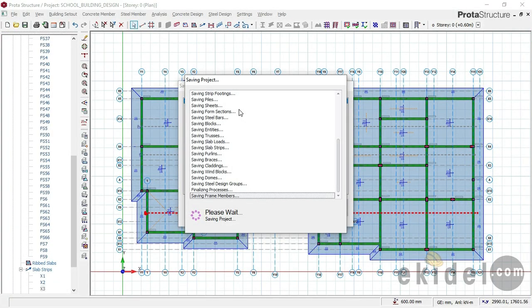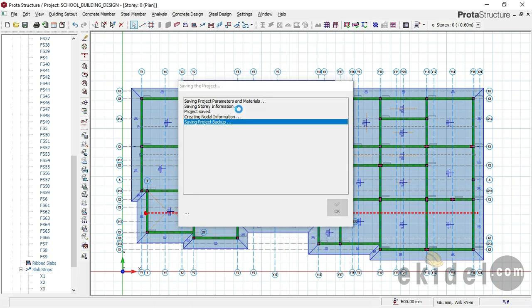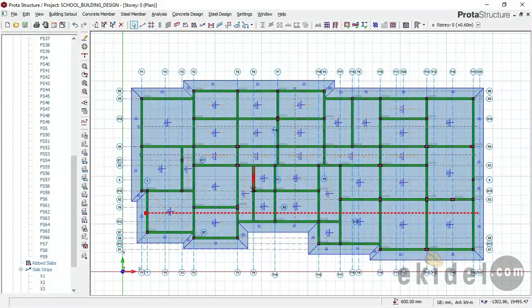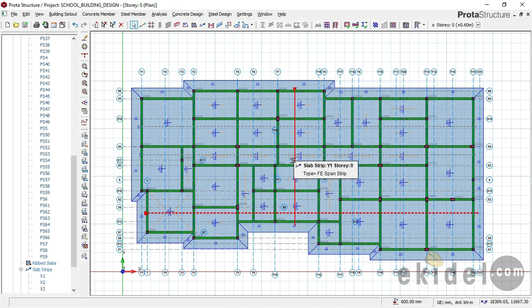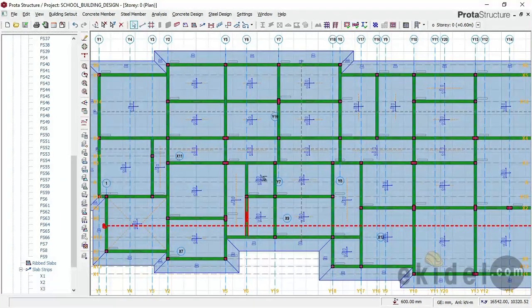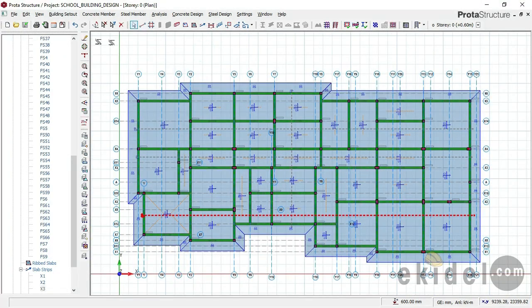If it is for a bigger building, use a raft foundation. If it is for a very small building, you have to use a wide strip foundation. And if that wide strip fails, then you can go ahead and use a raft foundation. Okay, so right now we have cut our strip in the X and Y direction, and also saved.